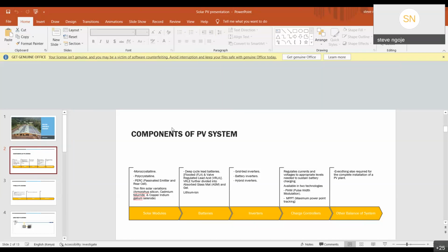But in exchange for that, the power at the input side will be equal to the power at the output side, in the sense that it will increase the current. While it is reducing the voltage, it increases the current. If I have a 500-watt DC input, on the output side I will still get my 500 watts, regardless of whether my module voltage has been reduced from 40 to 24. So for better efficiency and the best system, you need to always consider MPPT.